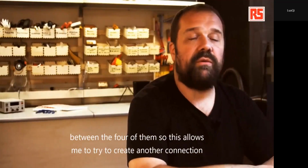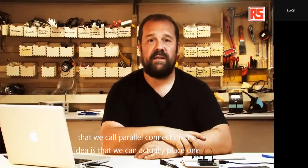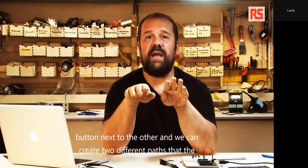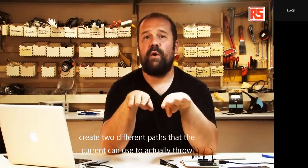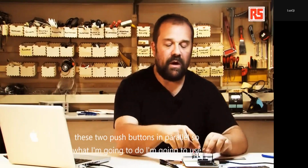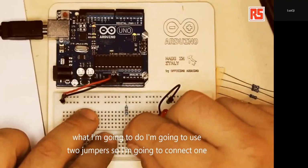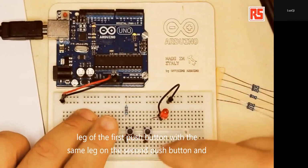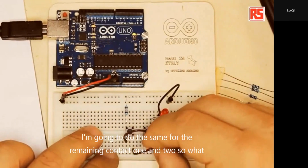So this allows me to try to create another connection that we call parallel connection. The idea is that we can actually place one button next to the other, and we can create two different paths that the current can use to flow through. Let's see what happens if we put these two push buttons in parallel. So what I'm going to do, I'm going to use two jumpers. I'm going to connect one leg of the first push button with the same leg on the second push button, and I'm going to do the same for the remaining contact, 1 and 2.